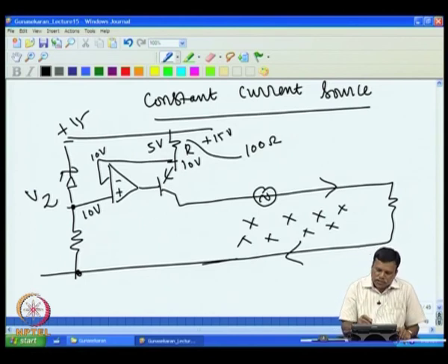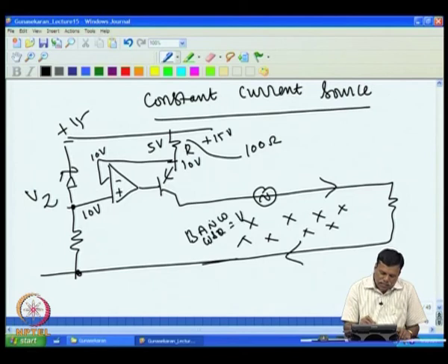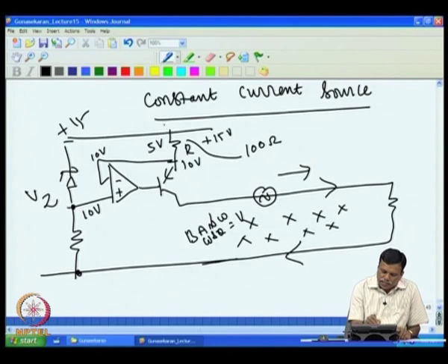This voltage is an AC voltage, because we know that B A n omega cos theta is the induced voltage, and here n is 1. So the magnetic field has induced a voltage here, and this AC voltage will not drive any current through this, because if this voltage drives a current, that current has to come from the supply only, and it has to go through this. There is no way this induced voltage can complete the path through the current source.